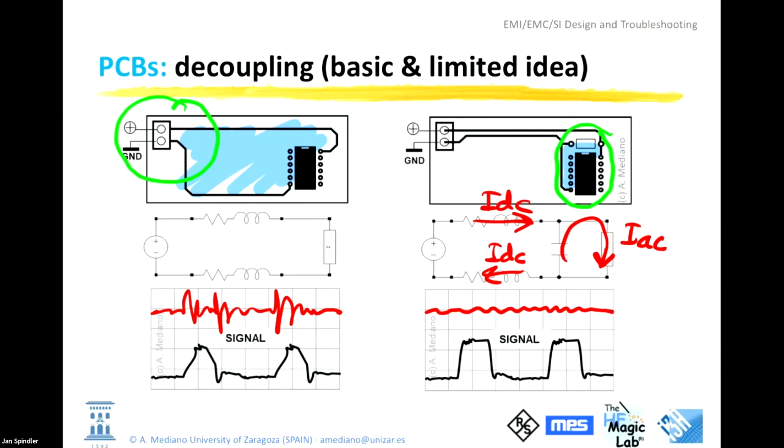But I am not interested in signal integrity. I am interested in EMI. And from the EMI point of view, what is very important is that the energy is in a very small part of your PCB, away from the connectors and from sensitive areas. If you don't do the decoupling in a good way, forget signal integrity, you will have the energy spread around the PCB. It's impossible to control this energy.